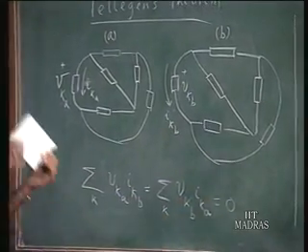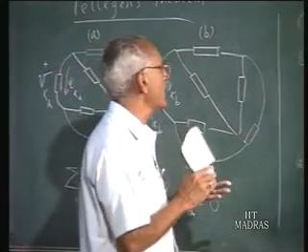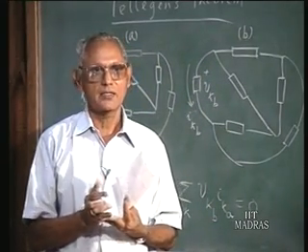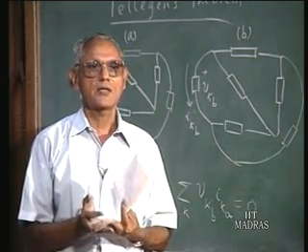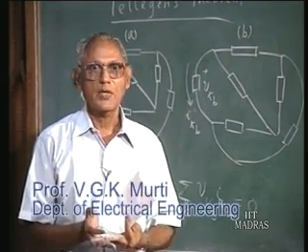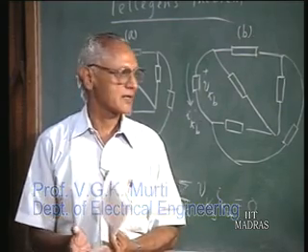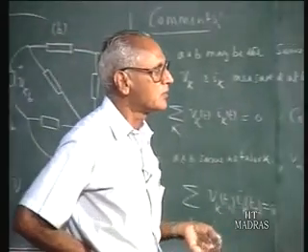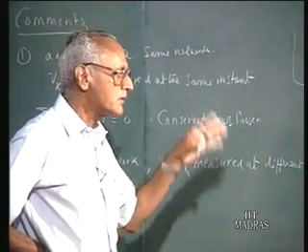It means as long as the set of voltages that you take satisfy Kirchhoff's voltage law, and the set of currents you take satisfy Kirchhoff's current law, and you know phasors, Laplace transforms and instantaneous values all satisfy Kirchhoff's current law, then you can use this theorem.